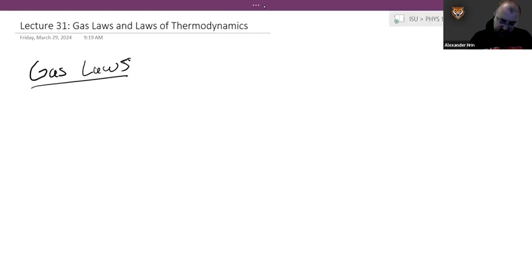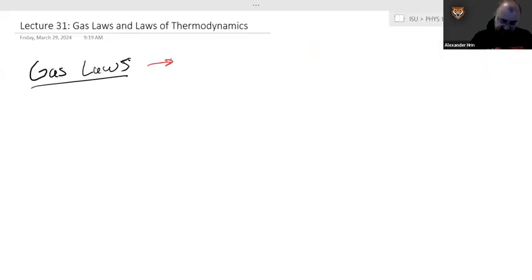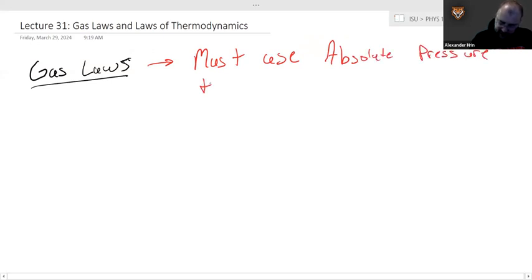Now, before I go too much further in this, I just do want to make a point that in these gas laws, any of them, you must use absolute pressure and temperature. Okay.